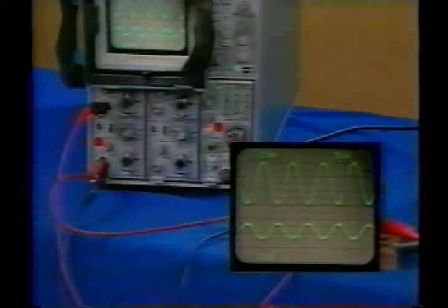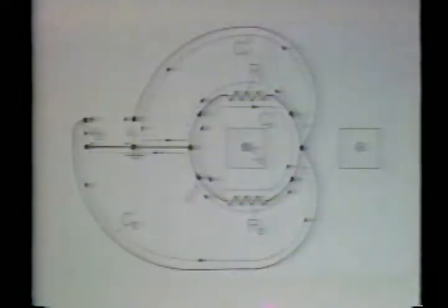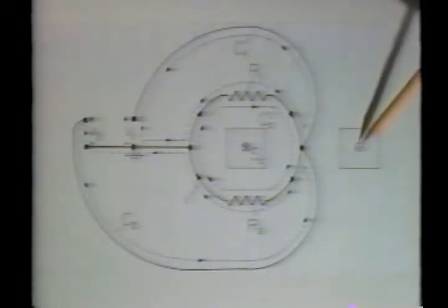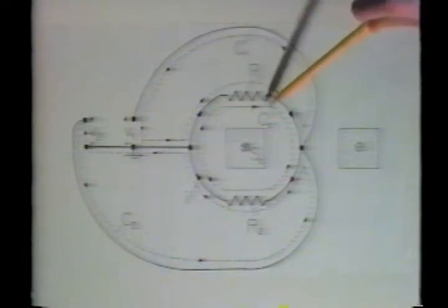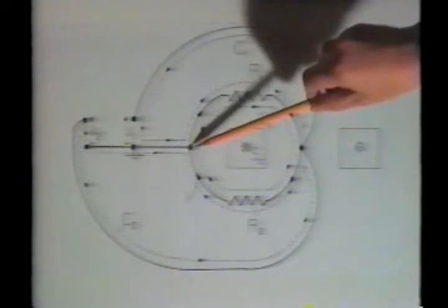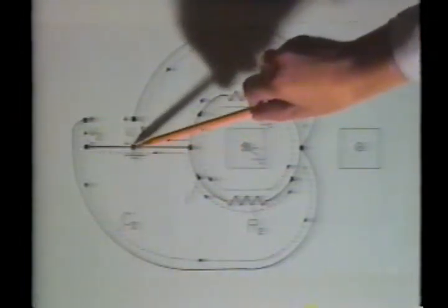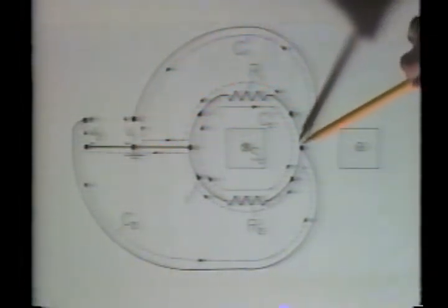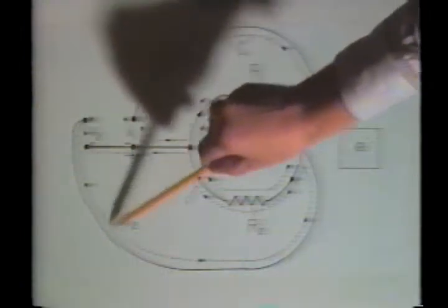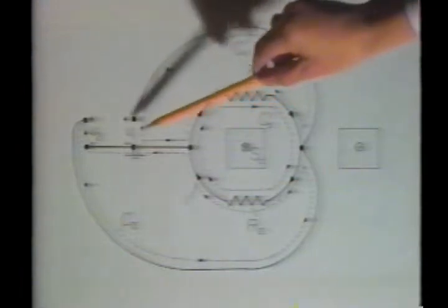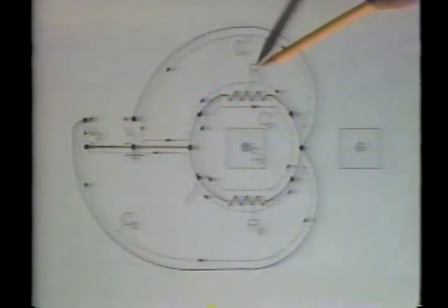The scope resistances are very large compared to either R1 or to R2. So the current carried by the oscilloscope leads is negligible. This means that if there is a current I through one of the series resistors, it must be the same as that through the other. Because it encloses the time-varying magnetic flux carried by the core, there is a current circulating through the resistors. The induction of this current is predicted by Ohm's law and Faraday's integral law.